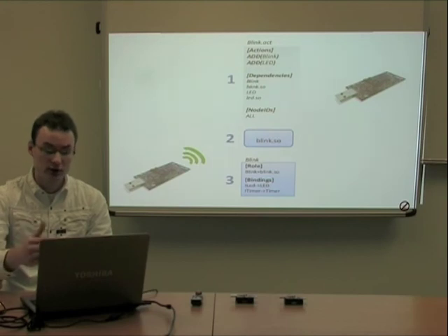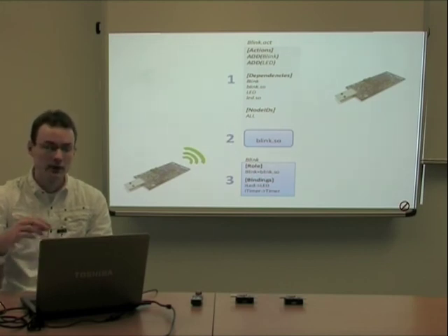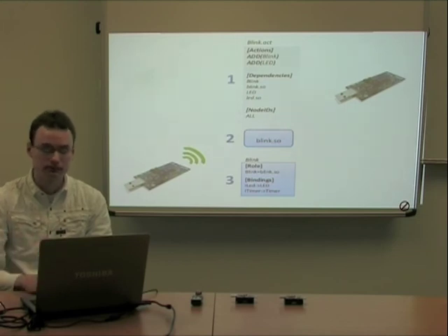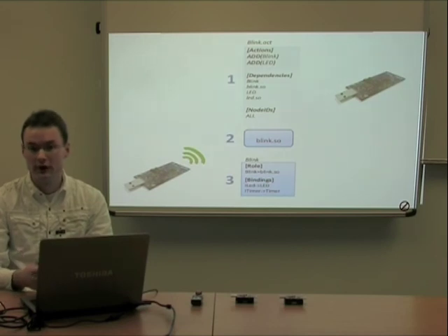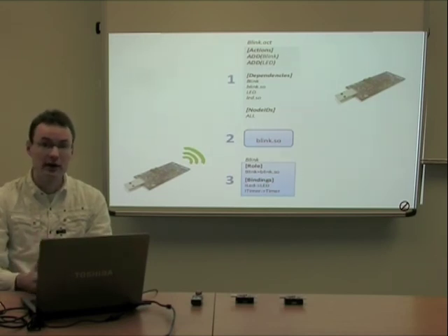And this just has two, which is add blink and add LED. The evolution script also has a list of dependencies, as in files that must exist in external flash before the script is executed. The second kind of file we have is the machine code itself, or the component which implements the machine code. And I've sent across both the blinking light application and the LED driver for this.